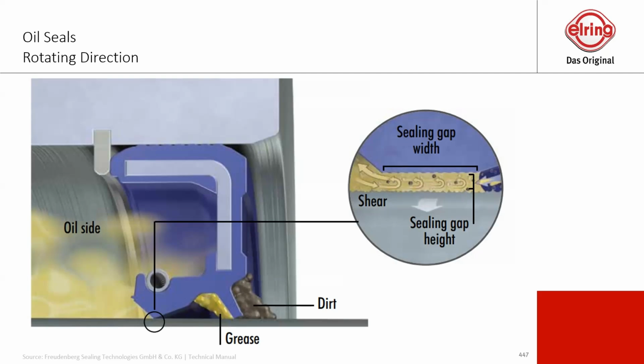So this is like here, in between at our contact point of the sealing lip against the shaft. We have an oil film which provides the lubrication. So what is the high risk? That some of this oil goes out here in front and causes a leakage. This is what we don't want to have. In this case, there's a clever function inside this oil seal, called a twist.